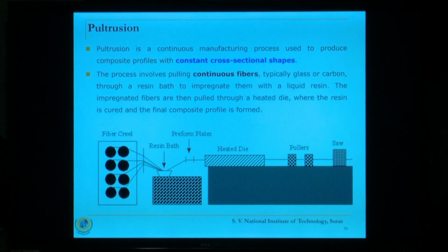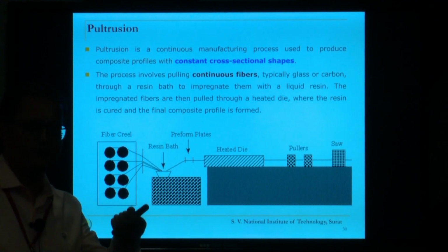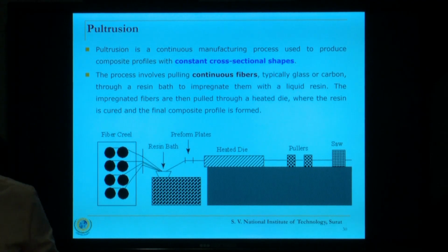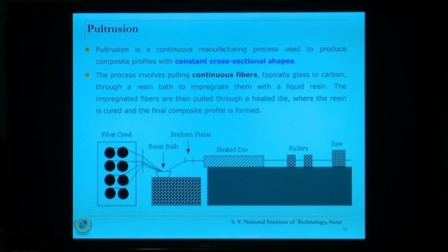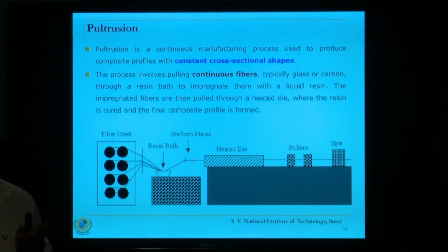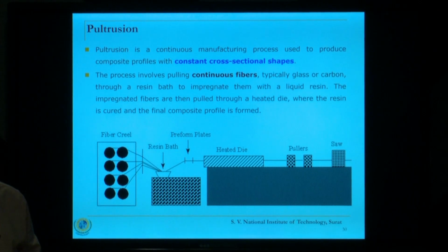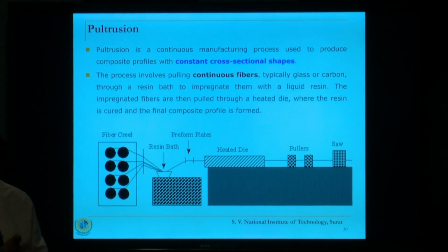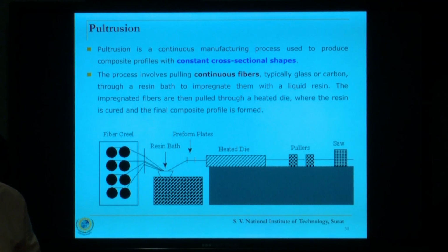So, pultrusion is extrusion wherein you pull the part. Okay, that is also an interesting process. Now, here the advantage is this is a mechanized process. So, you have more control over the process. You can set those parameters and you can have better control over the output.